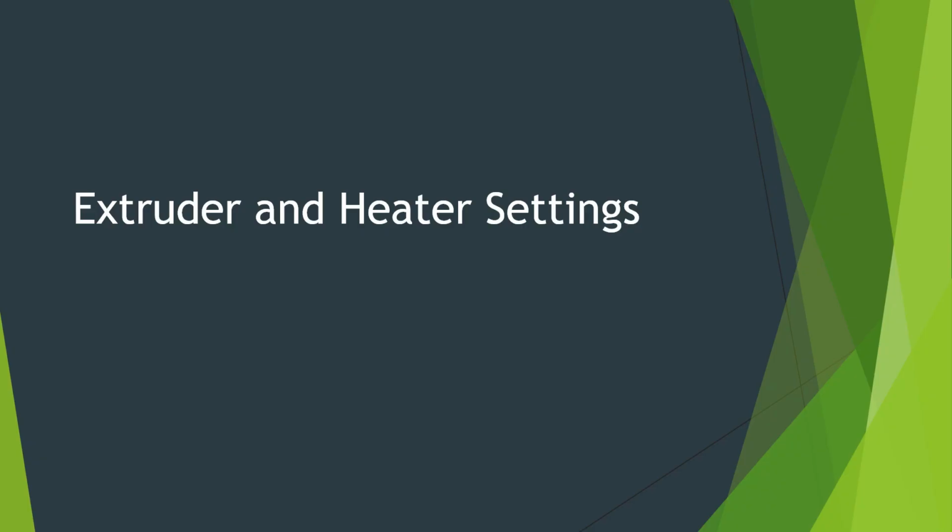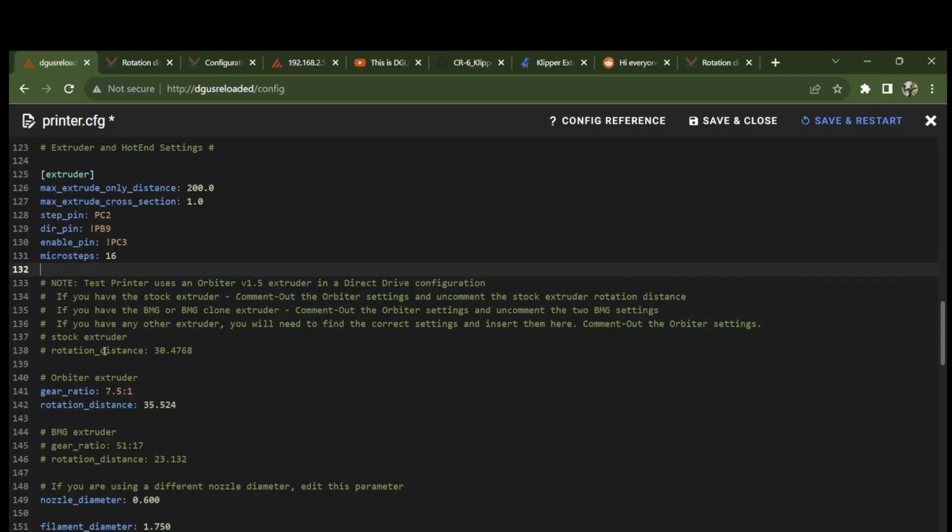My printer is a direct drive configuration with an Orbiter 1.5 extruder. So if you're working with a stock Bowden system, I recommend you change the max extrude only distance here from 200 to 1000, to be more compatible with your setup, and then you can tune that to your liking. And you'll want to change the extruder settings here, so you want to uncomment the rotation distance there. Take away the blank space so it's up against the margin, and you want to comment out the Orbiter like that. I'm presently using a 0.6 millimeter nozzle.